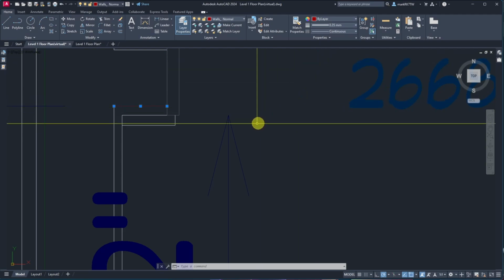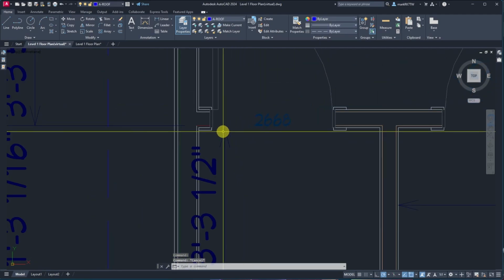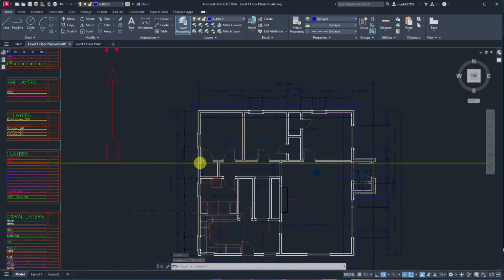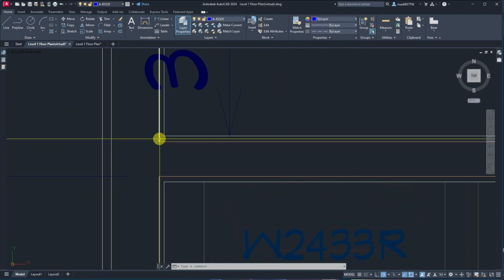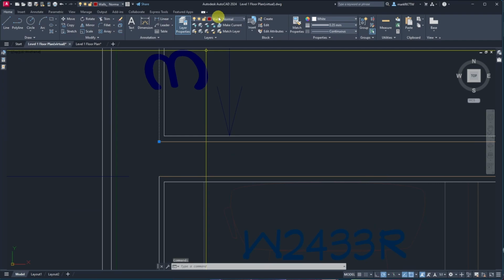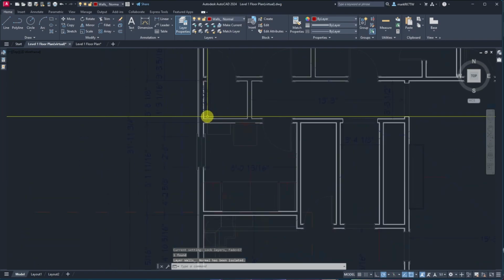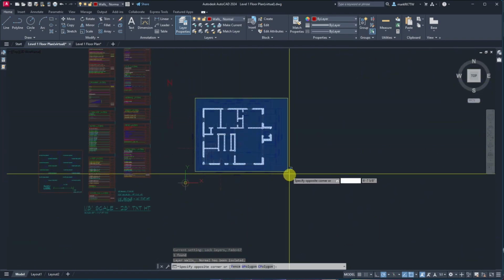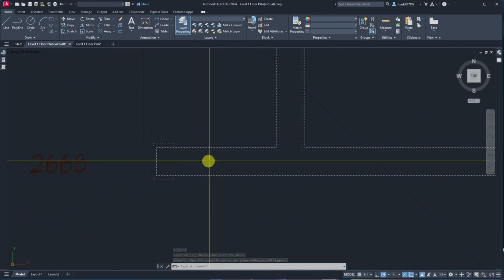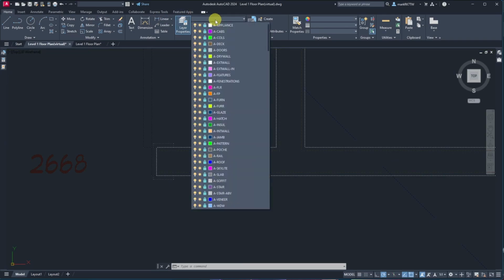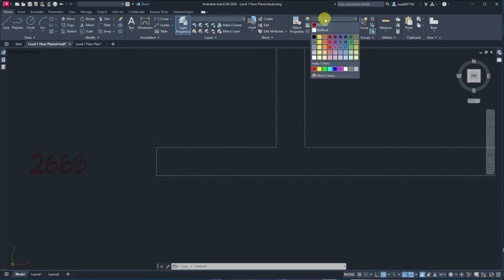So if I just switch it to by layer, then I could grab and isolate all those walls normal and make them all by layer. And then they'll all instantly be that color. So I'm going to grab one, walls normal, and then I'm going to take that and isolate it. So now all my walls normal layers are selectable. The rest are locked. So even though they're selected, they should not change. So when I change these to, oh, look at that. It changed to by